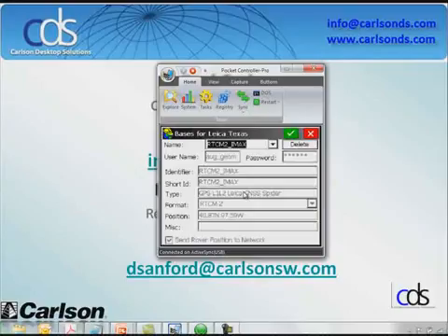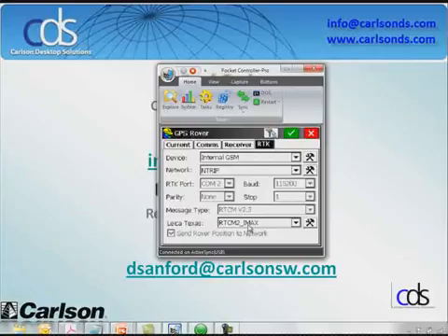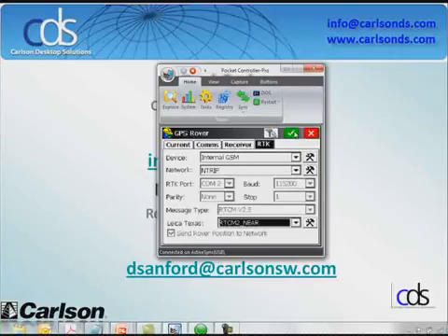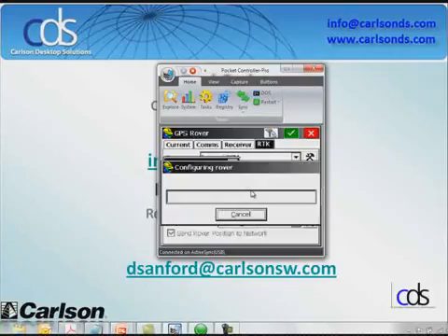This process takes a couple of seconds to do, but the amount of time the reference network saves over a base rover is almost immeasurable. Okay, and then again I tell it which type of corrections I want coming off of the base. I'm going to use an RTCM2 nearest, which means it'll go to the nearest base and give me a single baseline correction. If I wanted, I could do the max solutions, which is a true network-based correction. Once I have everything set, I hit the green check mark, OK.